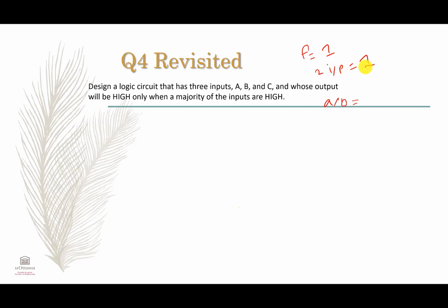If you remember the way that we solved it, first we started by writing the truth table, and since we have 3 inputs, A, B, C, here it's gonna be 0, 1, 0, 1, 0, 1, 0, 1, and here it will be 0, 0, 1, 1, 0, 0, 1, 1, and here it will be 4 zeros and 1, 1, 1, 1.